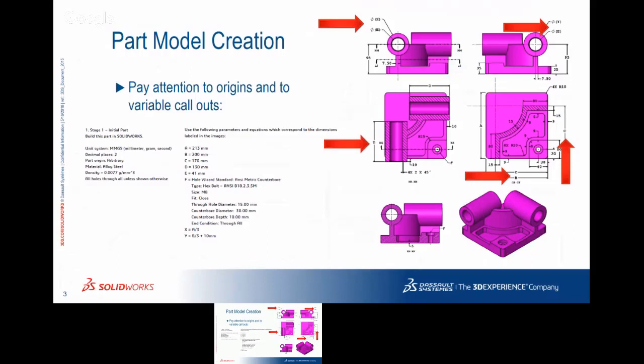The way the exam works, this is based off the very first part of the exam. We don't have the ability to see how you model something in terms of features. But like we were discussing at lunch, imagine a simple plastic cup. There are probably a few different ways to model that cup in SolidWorks. You can do an extrude, you could do surfaces, you could do extrudes on top of extrudes, but the simplest way is probably just a revolve, and you could do it in one feature. Certainly one way is going to be more efficient than the others.